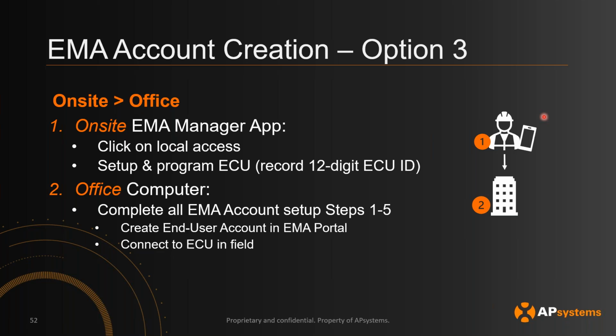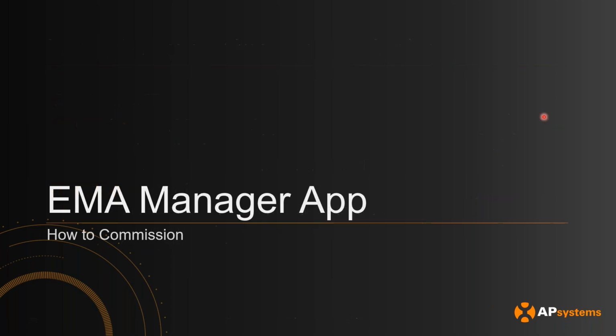But the main thing is that, if you have to do something on the site, the most important thing is to connect it to the internet. I would recommend connecting the microinverters to the ECU on site also, because you'll be able to know immediately if a system is working or not. So I'll talk a little bit about how to do that.